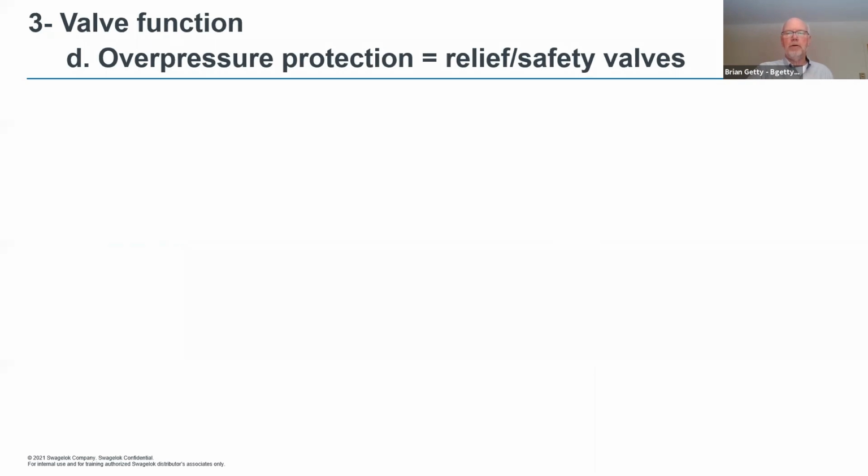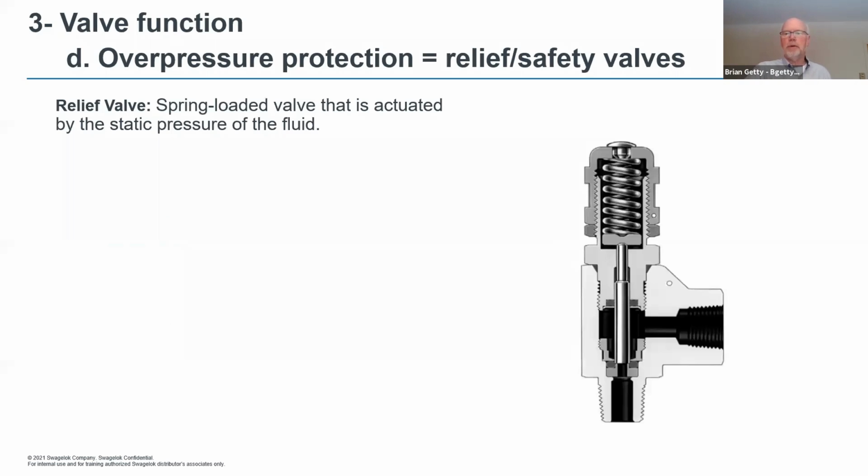Okay. Two, and we get into here. Here's a relief valve. Okay, to show you again, relief valve. And as I was saying before, this is a little more exploded view. Your pressure here would come, and it would of course push on your stem and allow flow through. All right, and then once that happens and the pressure goes back down, at that point the poppet here will automatically reseal.